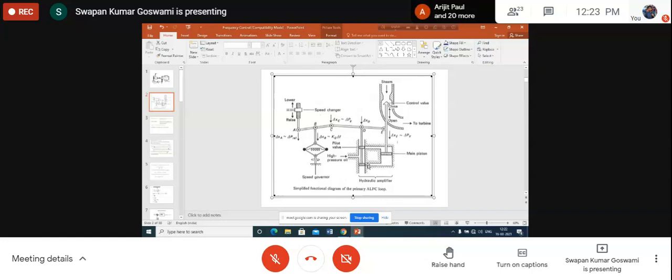So as a thrust is given towards the lower part, an upward thrust is given to the main piston, which will move up, and excess oil from this chamber will drain out through this opening. Because of the high pressure given by the oil pump, an upward thrust will be given here, so the main piston will be moving up.